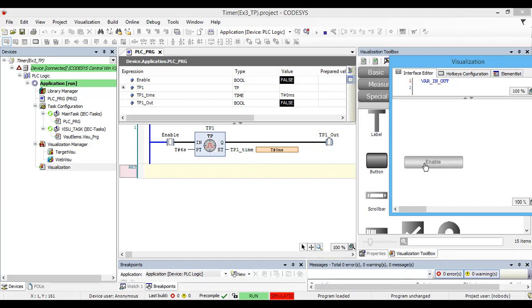And it's out. So when I release my hand, then it goes 0. So the time that I press this one, it starts counting. No matter whether your output goes high, then it resets at this. If I do anything, it doesn't matter. Right, that's all about the pulse timer. And so I will show you some more examples now.